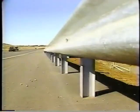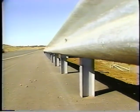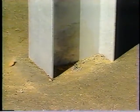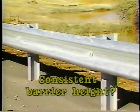The standard section makes up the longest part of the barrier and should be inspected as closely as the other sections, since it is the part of the guardrail that absorbs most of the impacts. Here are some questions to ask when you check it out. Are the posts properly embedded? Is there enough soil behind the post to prevent them from being pushed out on impact? Is the height of the barrier correct? Is it consistent through the system?